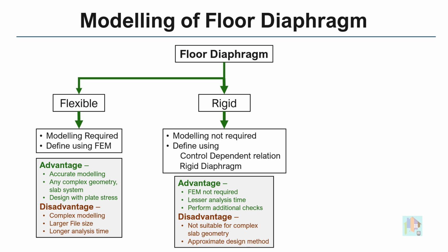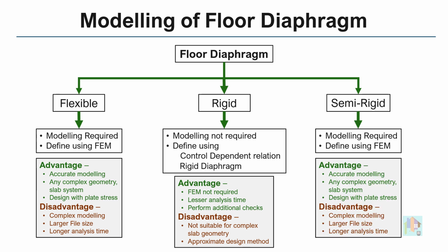I'll cover this later. Finally, we can define it as a semi-rigid diaphragm which simulates actual in-plane stiffness and behavior of slab. In this method, we need to model the diaphragm properly with plate mesh like flexible diaphragm. So similar type of advantage and disadvantage.